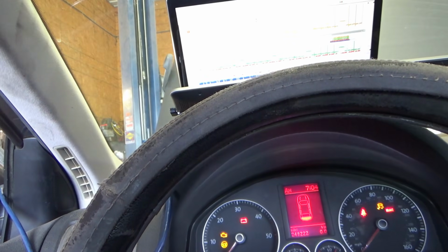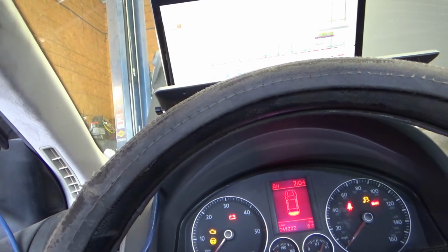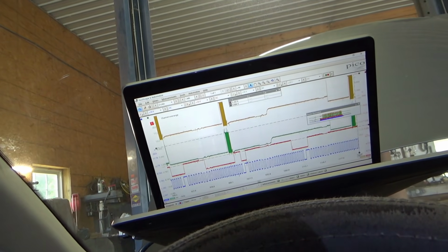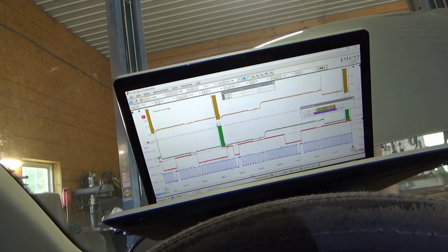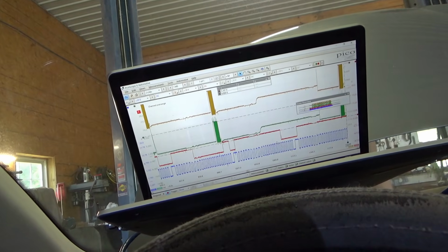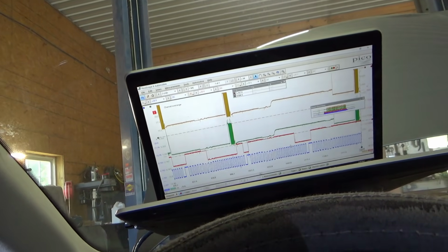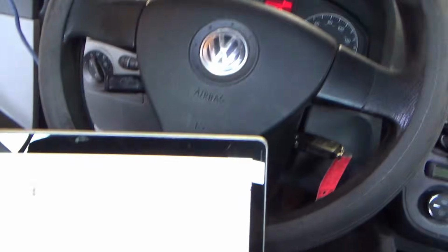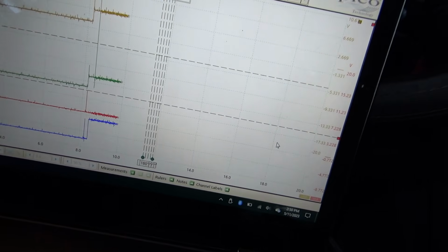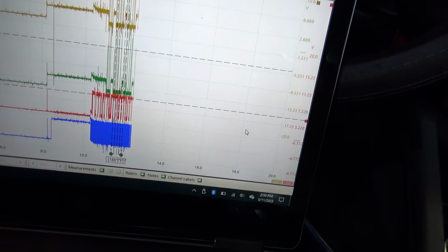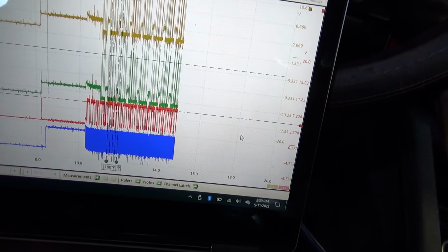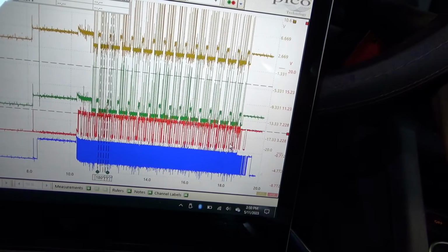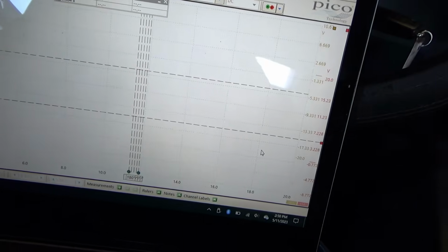The injectors are doing the exact same thing they were doing before, and now the cam is occurring a little later, right over the sync pulse. Maybe you can retard it just a hair more, go to the limit, see if anything changes, but man, this thing is really, really picky. Alright, cam is now fully retarded. Let's see what happens. That poor starter.